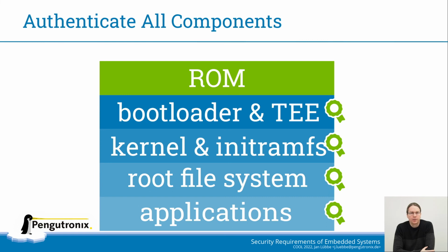So you have a chain of authentication from the ROM up to your application, and only a reboot is needed to re-verify everything. By having this, you can simplify your reasoning about trust and attack vectors at the higher levels, because you don't always need to keep in mind what would happen if something was modified in storage and an attacker's program was running instead of my own system.